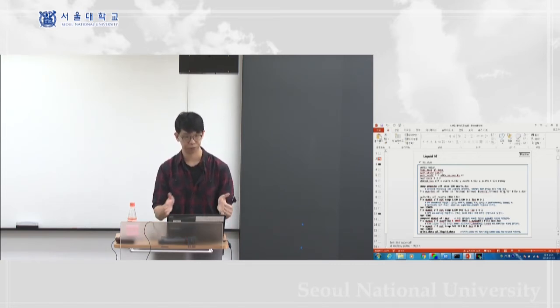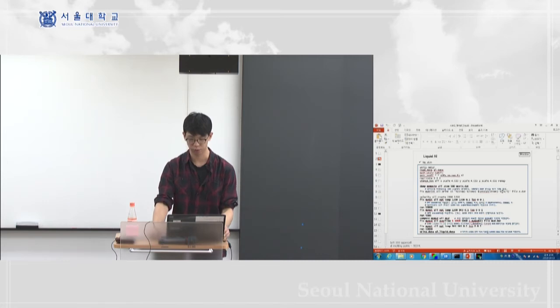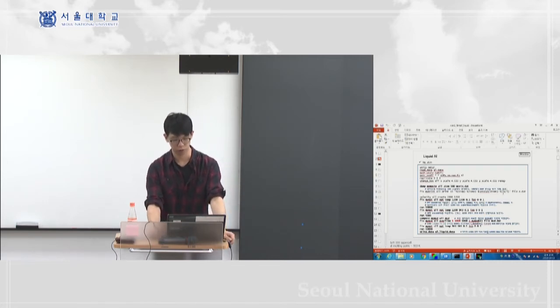Lx is the size of the box in the x direction, and since we made this 3x3 supercell, we have to divide it by 3 to obtain the lattice parameter. So we're gonna make it dump the lattice parameter with this Lx/3 command.